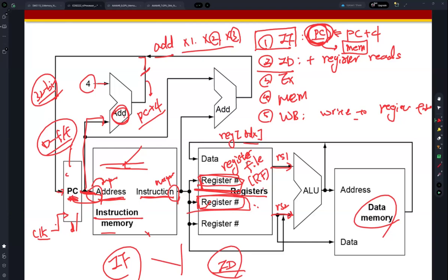But actually, a processor needs to include the decoder. In chapter 2, we learned how to encode. Encoding means that the assembly instruction is translated into the machine instruction. In order to figure out the type of instruction or the operands in an instruction, a processor needs to decode.